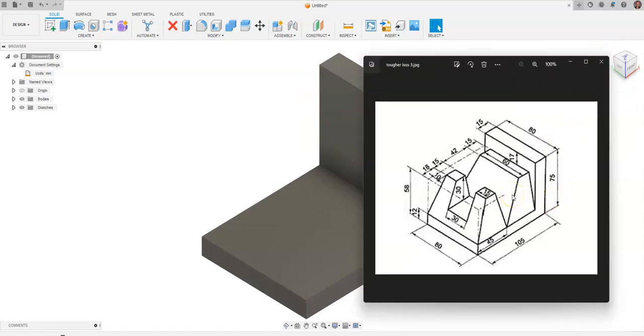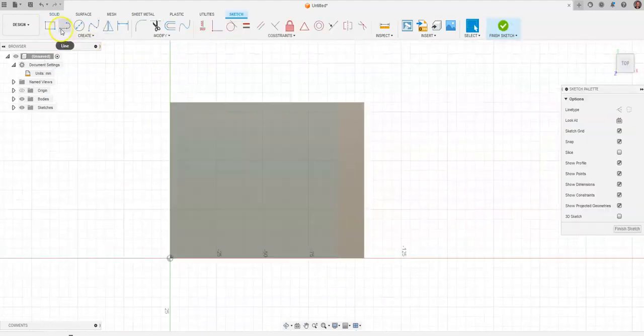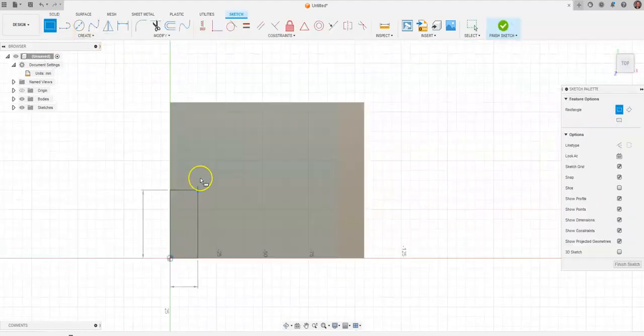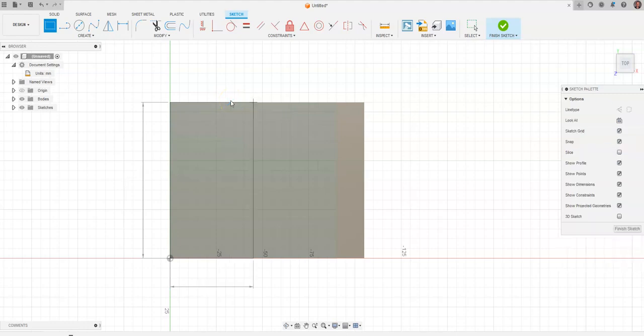Now what we need to do next is we're going to start creating these surfaces that we need to create these lofted views. And this line right here is 45. I know it's the full depth because I can see it go the full depth back here. So we'll grab a hold of Create 2D Sketch. We're going to click on this surface. I'm going to grab a hold of 2-point rectangle. When I drag up along the line, automatically it's going to snap to 80. I'm going to hit Tab, and I'm going to go to 45, and I'm going to hit Enter.